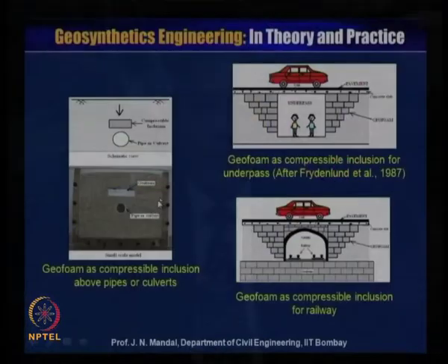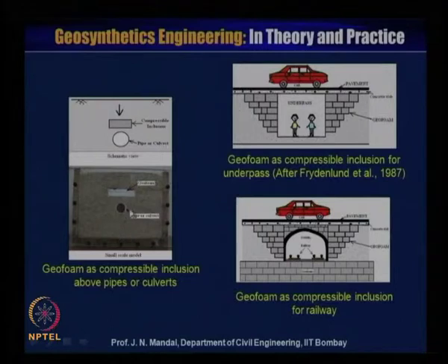So here you can see this model. This is the pipe and this is the geofoam. Initially, if we provide it at a certain depth and apply the load, there is a possibility of bending of the pipe, so you need to increase the depth of the filling material.